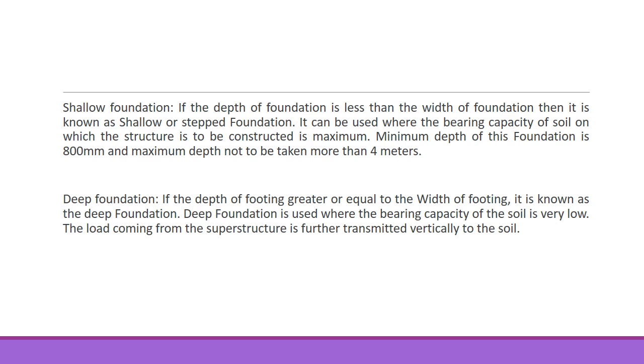About deep foundation: if the depth of the footing is greater than or equal to the width of the footing, it is known as a deep foundation. Deep foundation is used where the bearing capacity of the soil is very low. The load coming from the superstructure is further transmitted vertically to the soil. In this condition we use deep foundation.